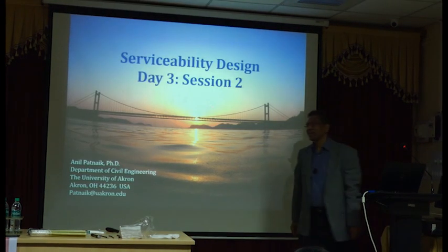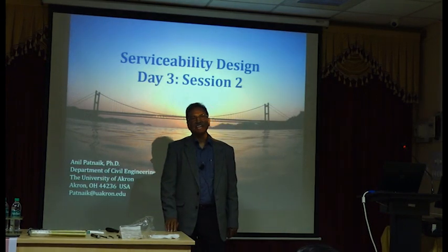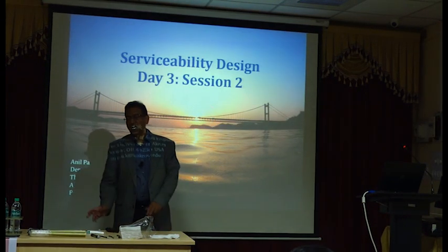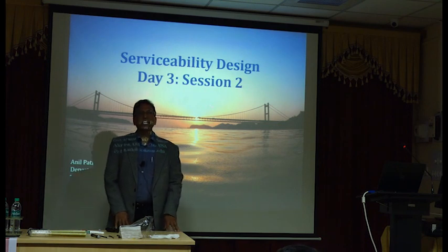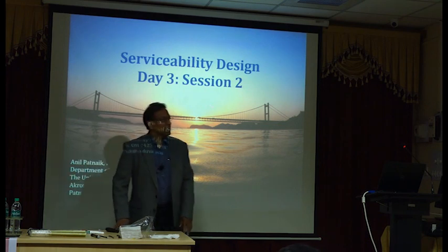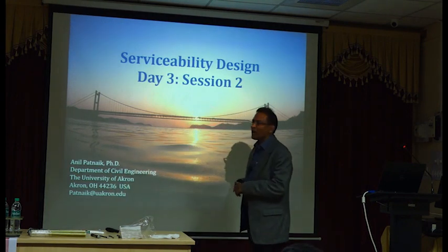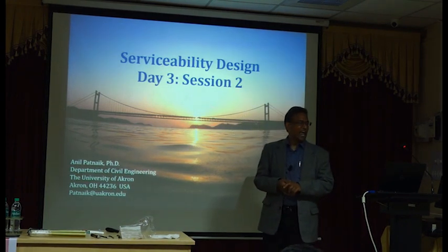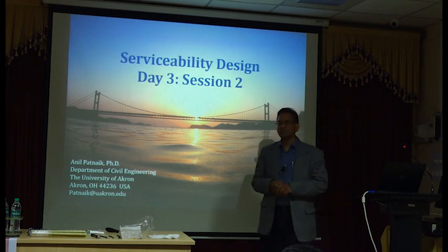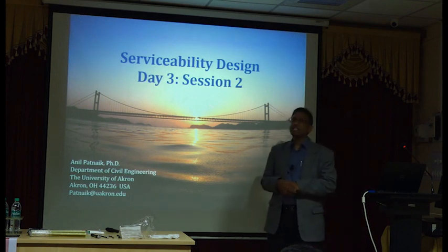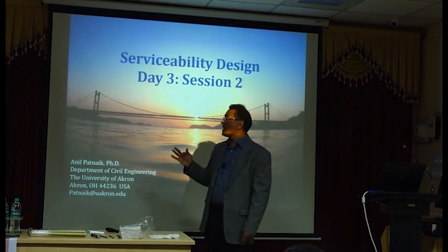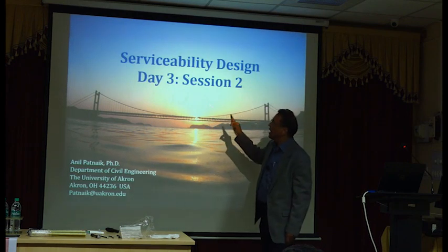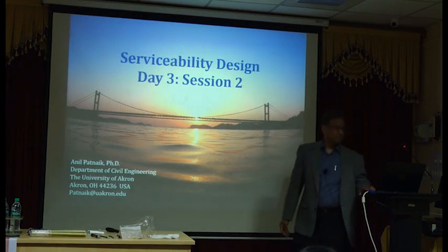Serviceability design. Okay, now we are going to address serviceability design. Until now we talked about strength, moment strength. Now we are going to talk about serviceability. In case of FRP reinforced beams, there are two things that we check normally: crack widths and deflections. We'll also check creep rupture stress, but that's at a later stage. First we'll start with crack widths and deflections.